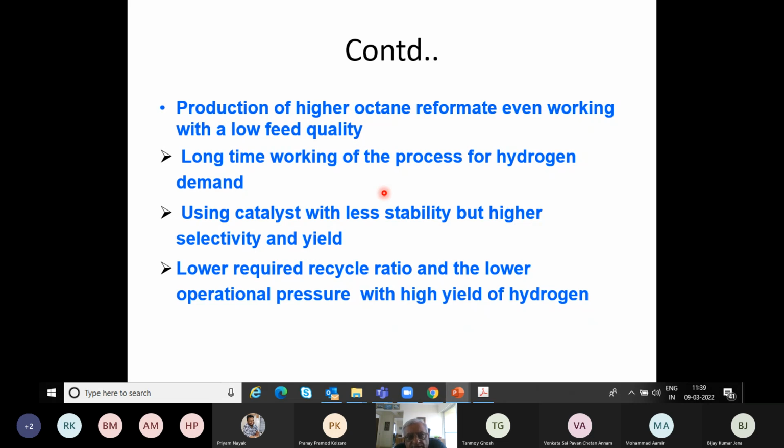And so typical catalyst suppliers guarantee a life of 5 years where the catalyst would be the same in terms of its activity. But after 4 years, you can start seeing the deterioration in the catalyst activity. And maybe around 5.5 to 6 years, it's just about the time that you would like to change to new catalyst. Because after that, you start losing money if you continue to operate that catalyst.